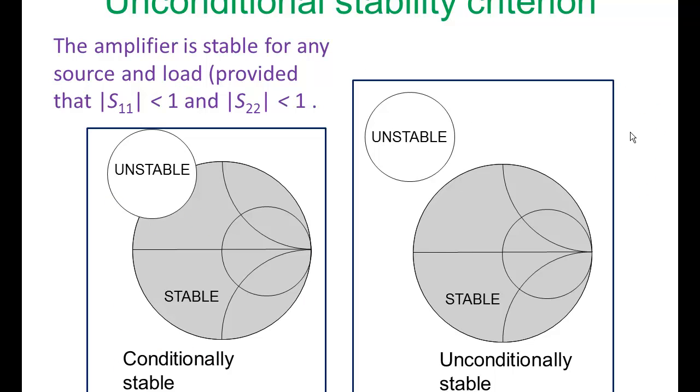Now, we usually like to design amplifiers to be unconditionally stable. No matter what happens, we want to make sure the circuit is stable. So our previous discussion refers to ensuring stability when we are at low frequencies and at high frequencies. The active device we're designing with will be stable at 8 GHz, no matter what the input and output matching networks will be, but we need to pay particular attention at low frequencies and at high frequencies. So here are our two situations of stability.